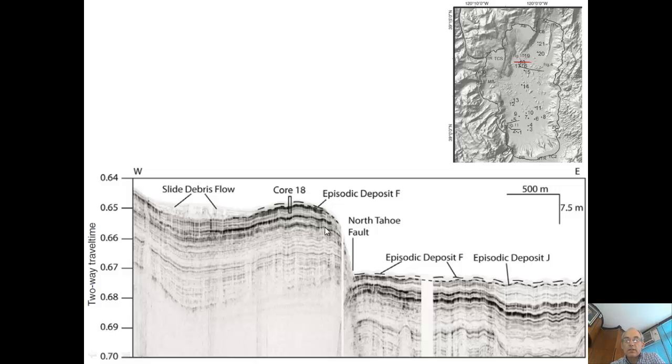So what they can do is, it's hard to get individual earthquakes to really do true paleoseismology, but we can do short-term slip rate studies, if we can date these sediments. They were doing coring, several meter deep cores, but you can imagine slightly longer cores and you could date these sediments. So this dark one here is probably this one, and you almost have the age for it. So you could get a short-term slip rate on this fault, and that would be quite useful. And then if you have a map of it, you can get the length, then you can back calculate the expected slip per event, and you could calculate an average occurrence interval knowing the slip rate and the length. So this is a really spectacular toolkit for us.